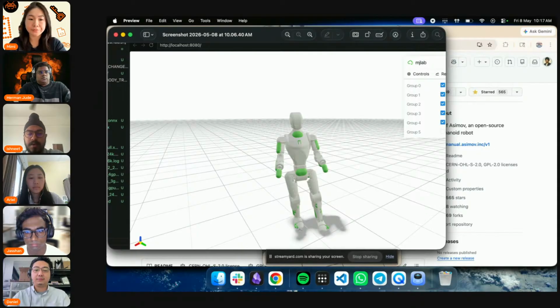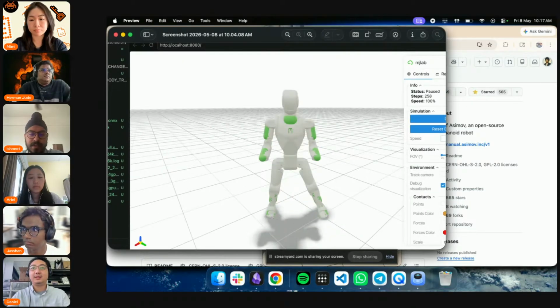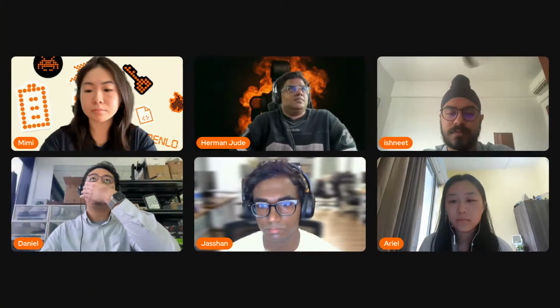It gives the policy headroom to lean and use its ankle roll so much, but in reality, it doesn't have that. After we rectified the XML and went back to an XML more aligned to the mesh, we were able to fix the sidestepping issue because the model is able to actually know how much foot room it has to bend its ankle, and so on. So this solved the sidestepping issue, but we're still solving the forward walking issue.